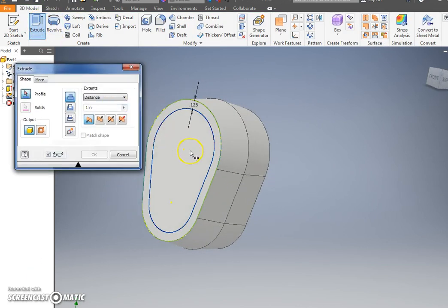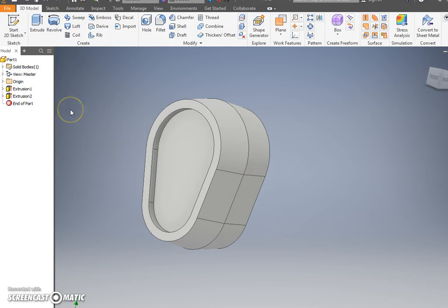Okay, easy enough. Press finish sketch. Okay, simple extrude, click here, it's going to go out. I want it to cut in. So if you automatically click the in button, it should default to cut. Otherwise, you just click the cut button and it knows to go backwards. So I'm just going to go 0.1 for right now. So that sketch is now done.